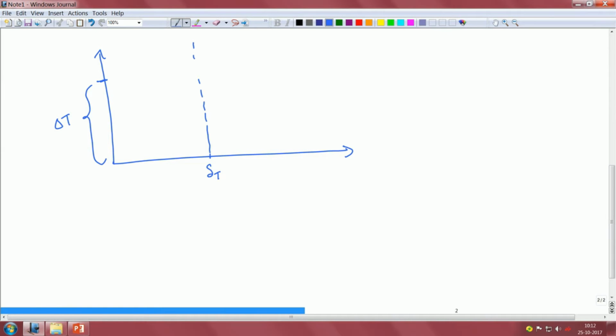In this zone, for Prandtl number much greater than 1, within this delta t, from here to here, the temperature starts at delta t, that is the maximum. It slowly goes down to something like 0 here. It is more asymptotic. So, that is the temperature profile.